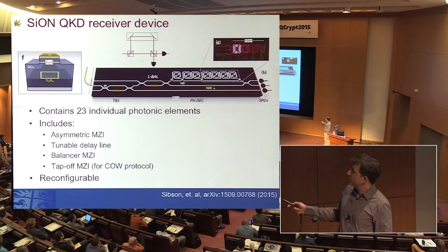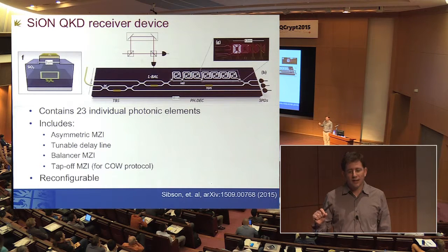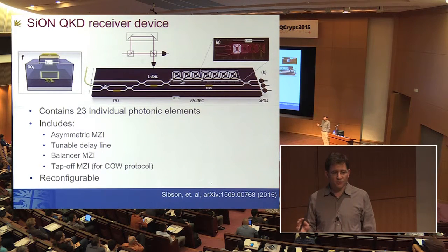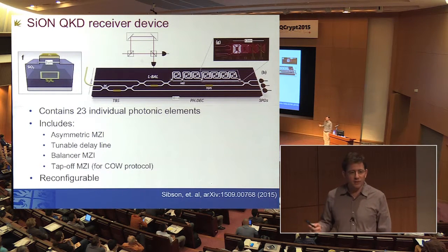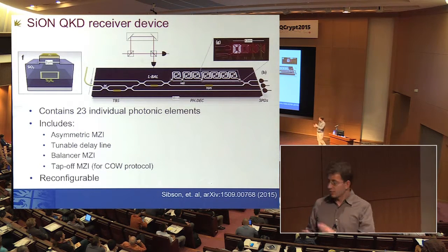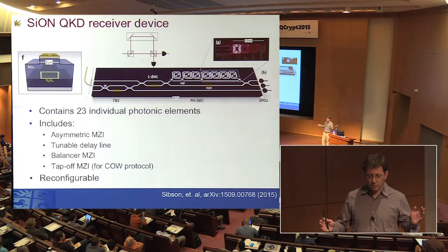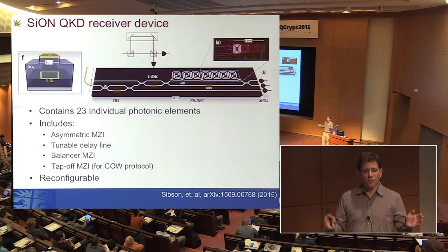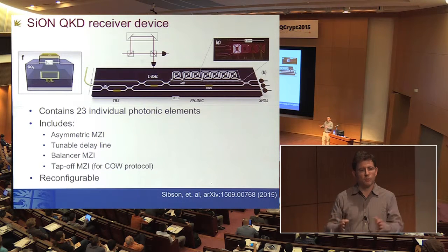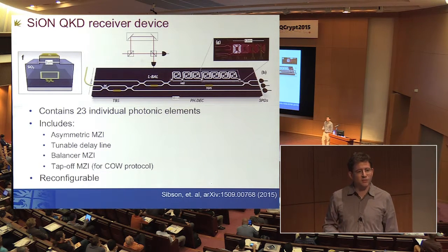We then use this phase shifter to calibrate and tune the system to get the minimum quantum bit error rate. And then once we set it, as long as we've got decent temperature stabilization, which for these sorts of circuits is no problem whatsoever, the whole thing remains completely stable. And you contrast that to a fiber system or a bulk system where you're having to stabilize the temperature over a much bigger range. We're stabilizing the temperature now over literally just a couple of centimeters. Okay, thanks.